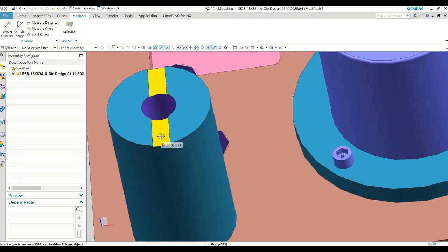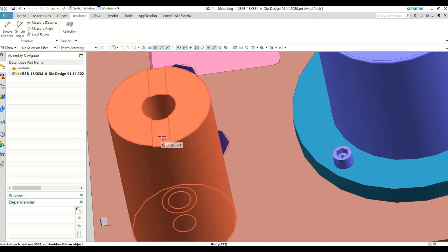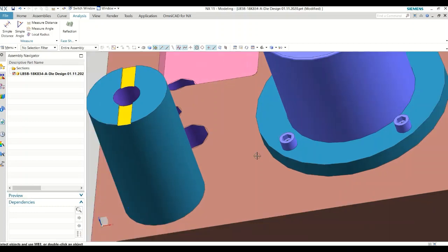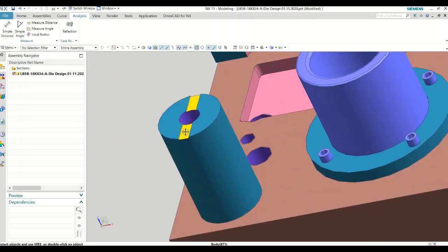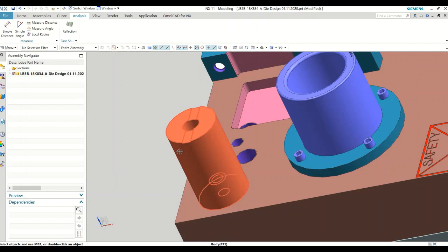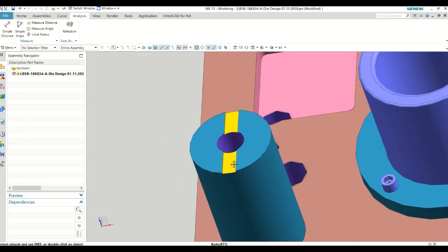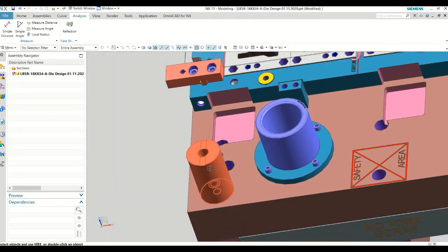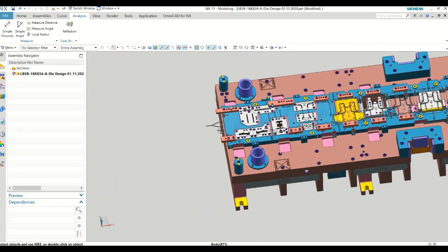The groove thickness is 1.27 mm, that's 0.050 inch, we say 50 thou. It's an inch standard in the USA, our customer end. Even if they have metric, we maintain 50 thou. So this is 1.27 millimeter deep.